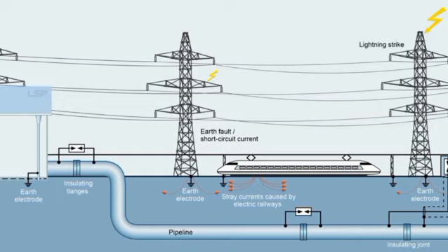For surge protectors, this parameter is defined as the peak value of the current through the surge protector when it is subjected to an 8/20 microseconds waveform impulse current injection. The standard nominal discharge current values are 5 kA, 10 kA, 20 kA, 40 kA, and so on. The nominal discharge current value chosen should match the expected surge current level in the application.